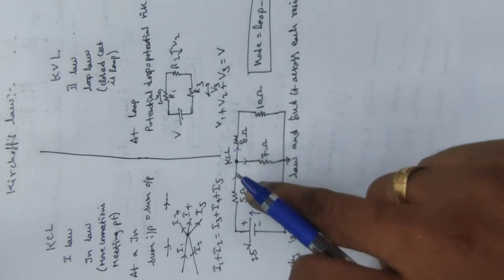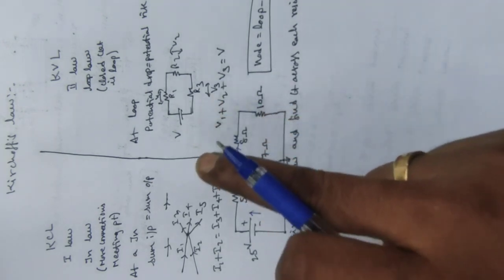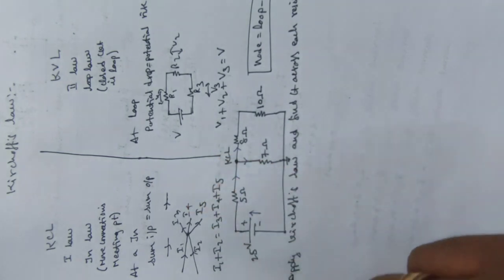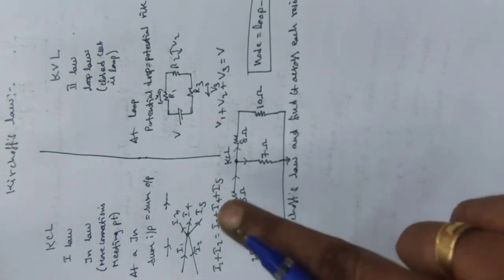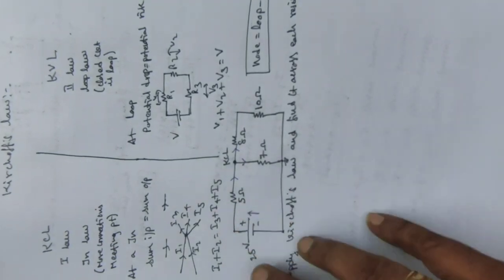The same current direction is what Kirchhoff's voltage law should follow. So while you apply the voltage law, you should not change the current direction which is assigned by Kirchhoff's current law. That is the important thing you need to follow.